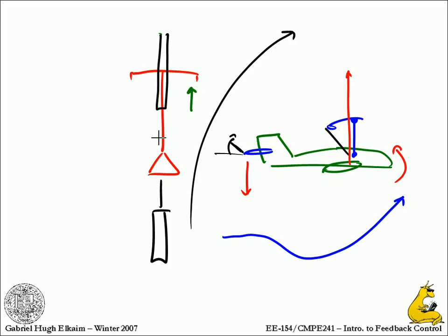So instinctively you turn away because that's what you do in a car. You yank the wheel away from the obstacle. But in this case, you turn into it. So the distance that he goes the opposite direction, is that directly related to how fast he was going? It's related to how fast you're going and how much force you push on this. So when Sheldon is on the bike going down, if he pushes gently, he'll turn slowly. If he pushes hard, he'll turn fast. But it is related to the speed.